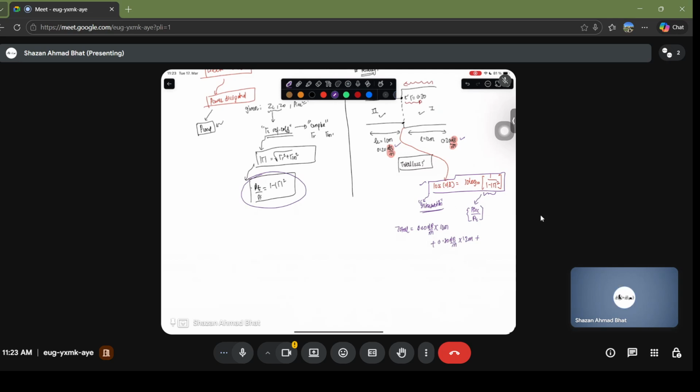Plus this particular loss, whatever the number will be. So this will be the total loss, so that everything comes out to be in decibels. You need to make sure that you don't obtain it in decibel per meter. You just multiply it with the length scale so that the overall power comes out to be in decibels. That is the essential concept in this microwave topic.